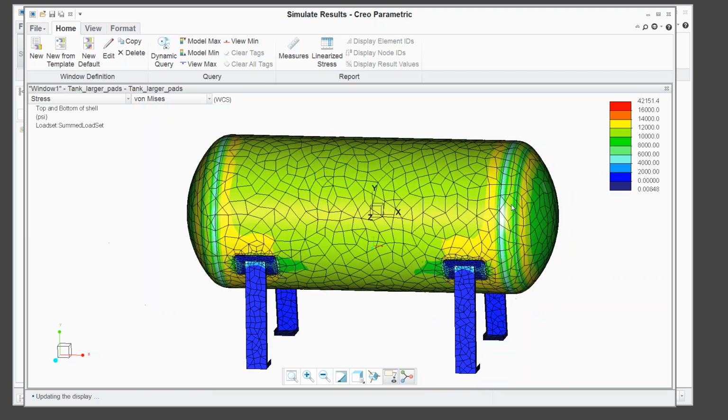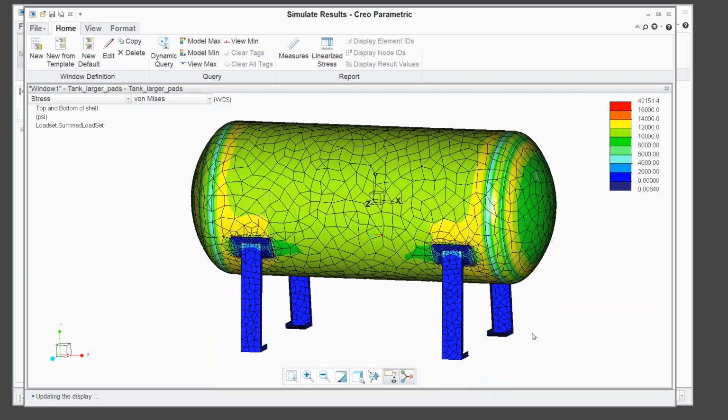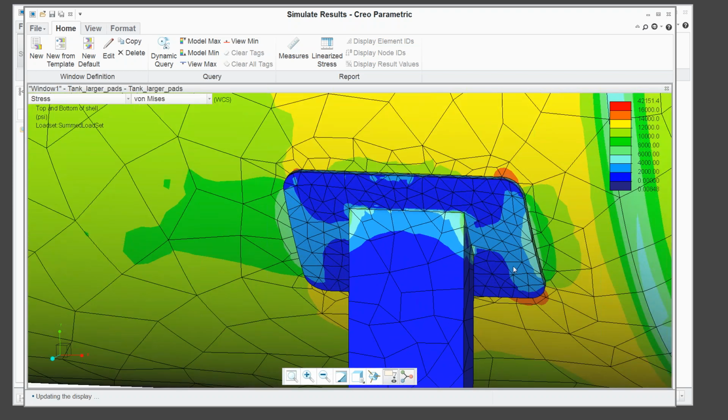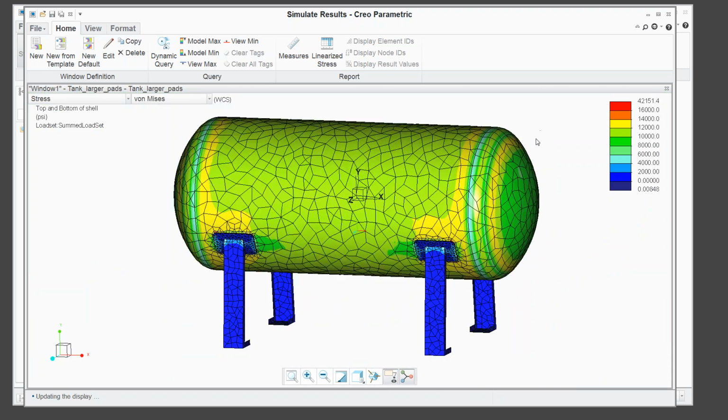If you look at propane tanks in real life, you will see most of them have a hemispherical end, and there's a really good reason for it. It's because you can get rid of this stress and probably make the things thinner, and they work just fine. But what I wanted to illustrate here was that we still have about the same kind of mesh quality as we did before, because we used the same rules to create the mesh. So as rule-based mesh refinement, it is auto meshing, and you can make changes to the design. You don't really have to give much more thought to the mesh unless it's a real major change. All right, so that's the deal there.